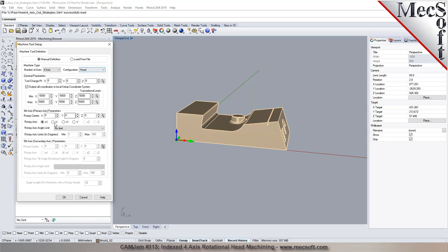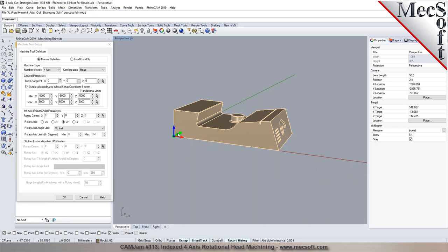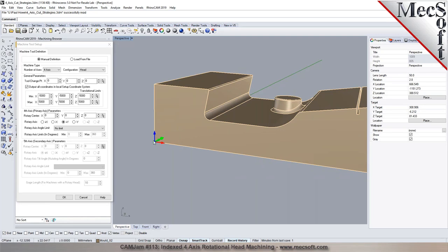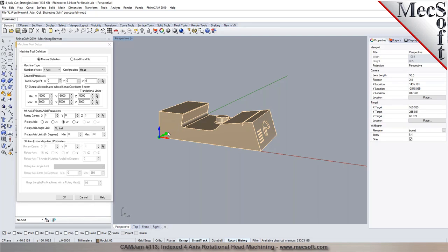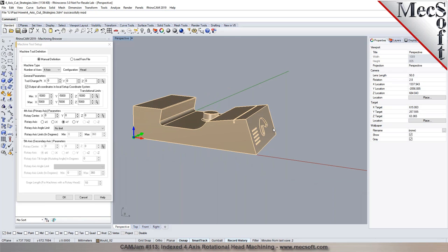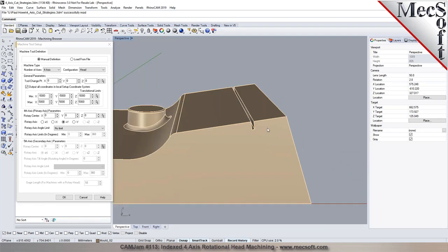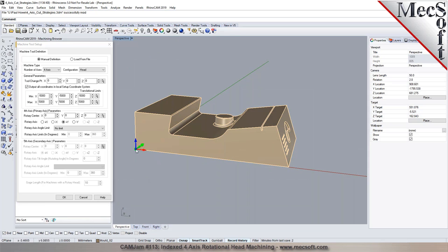Okay? Yes, and that's fine. I understand that. The rotary axis is going to be defined about the y-axis based on how your machine tool is built. So that would be plus Y, or it could be minus Y, depending on how the rotations are handled. The plus and minus is determined by the direction of rotation. If you select plus Y, you point your thumb in the direction of this arrow, the rotational axis. As you roll your wrist towards you, that'll output a positive angle. So if the tool is perpendicular or normal to this face, you would see a positive angle, like a B-axis angle being output for this. Yes. And if you're cutting the slot, you might get a negative angle because you're rotating in that direction. So the positive and negative depends on how your controls are set up on the machine, and you can pick Y positive or Y negative. Okay, I'll have to check that once the machine arrives. Okay. Yeah, I'm not 100% sure. So basically we output based on the right-hand thumb rule here.